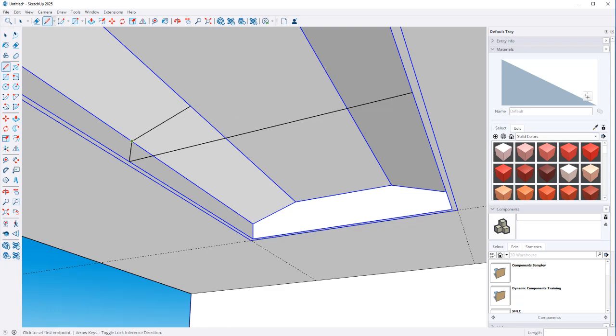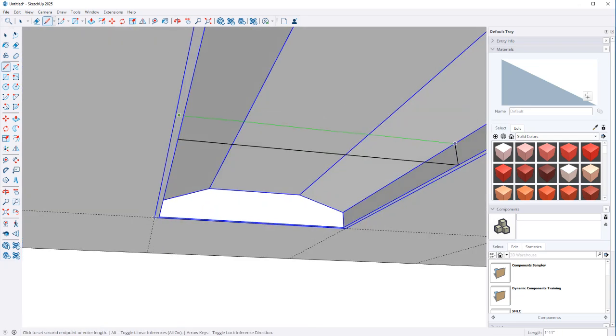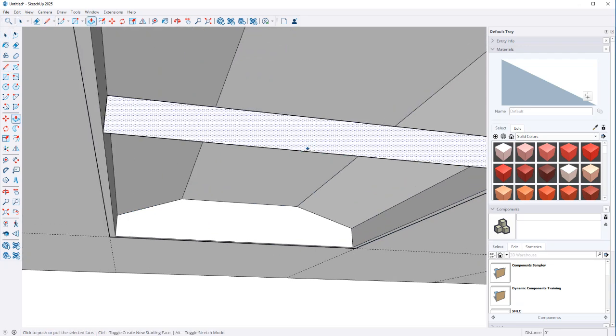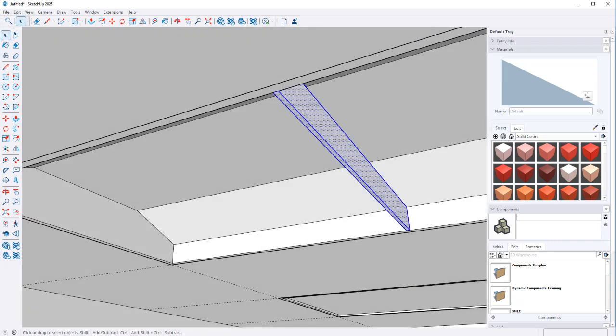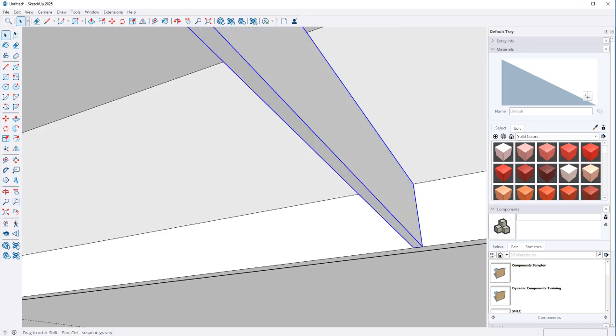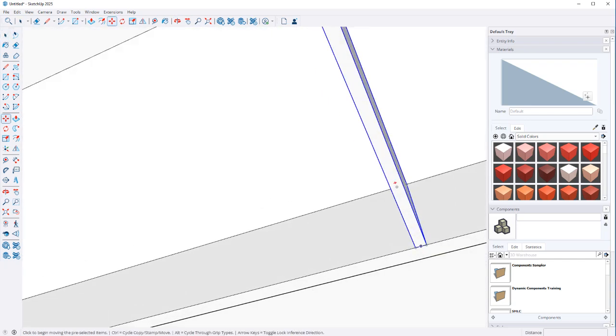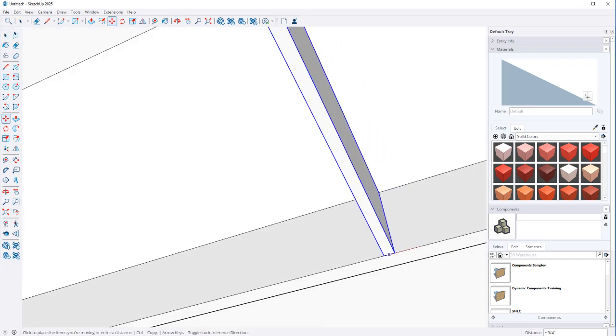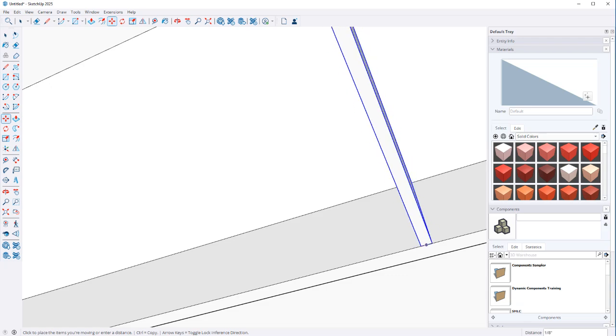Oh, except this doesn't go all the way to the top. It just comes across here, this little reflector. And then I'm going to make it, let's make it a 1/4 inch thick. So 0.25. Doesn't matter which way I'm going to go on that. But I am going to make it a group, and then I'm just going to recenter it. Whichever direction it needs to go. Is that center? Yeah. Okay.